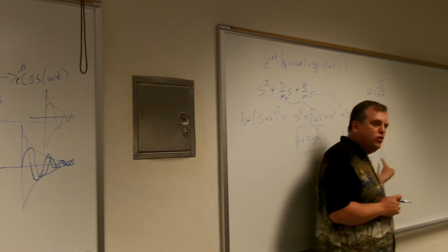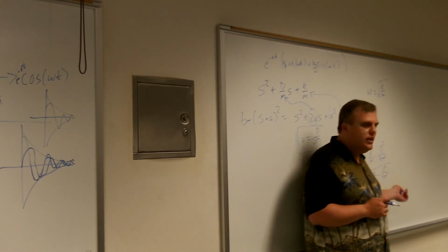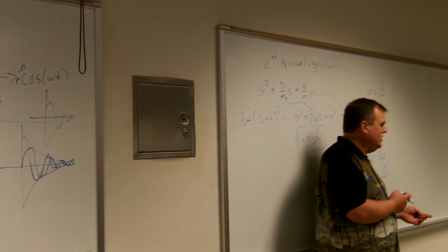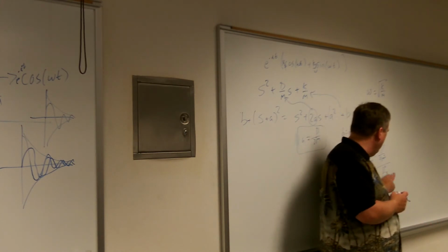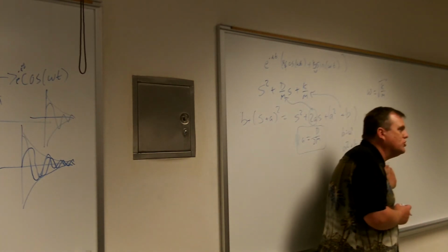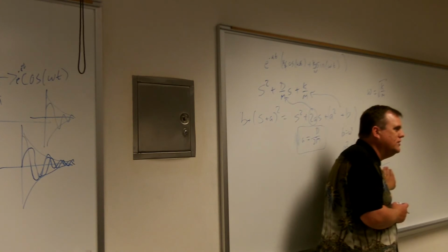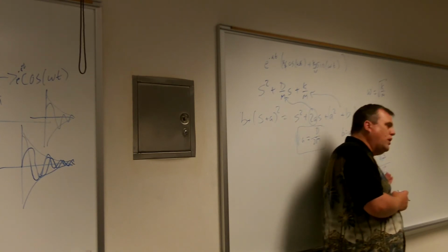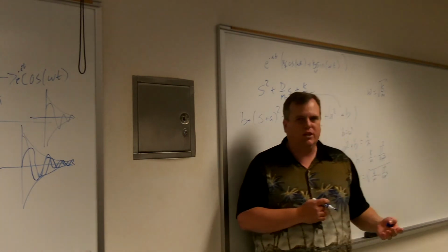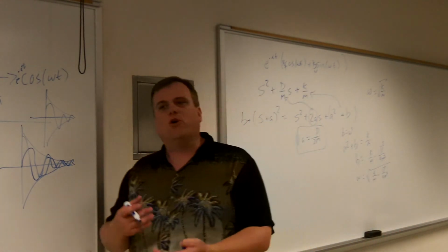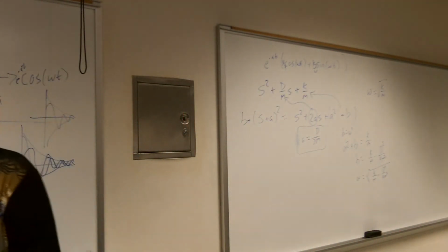You can now see exactly what happens when I add damping. I get a minor perturbation of that. It just changes slightly. Right? So if D equals 0, this reduces to the result of the simple undamped system. When D is positive, it moves away from it and it changes the frequency. So as you add damping, your frequency changes. We call that the damped frequency.